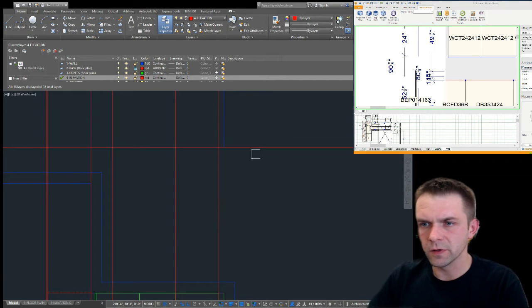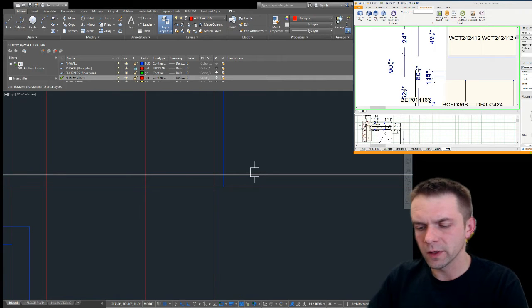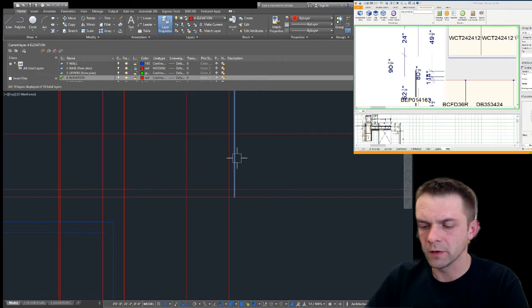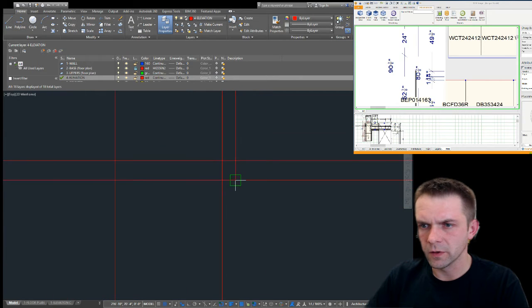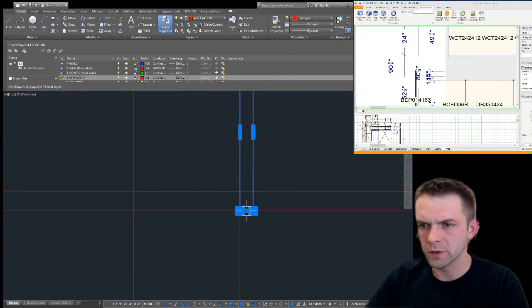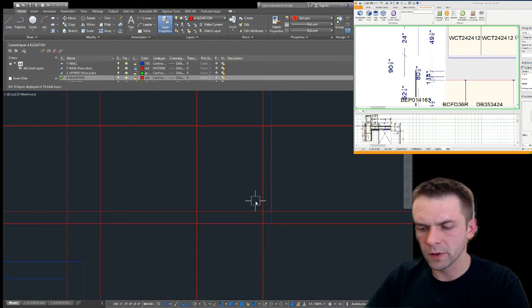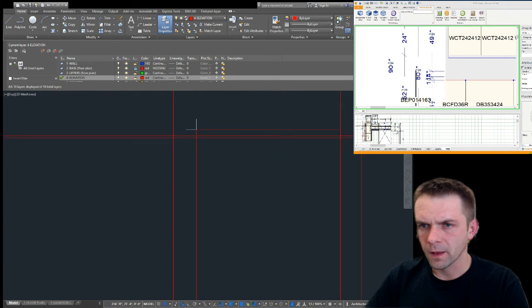So again, this is using our standard height. Toe kick is always 425. 34.5 is the height of the cabinet. Offset 0.25 is always for the door. REC. So this is a filler that goes to the floor. Actually, this one goes here. REC. This is a cabinet that goes here.